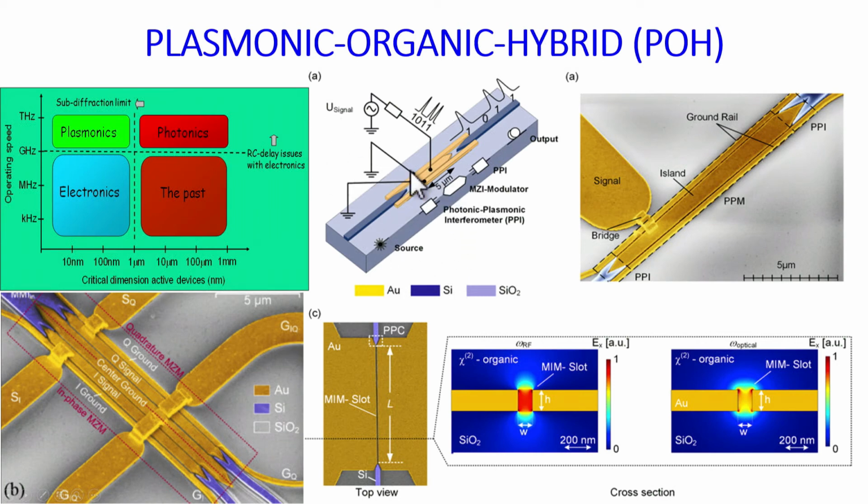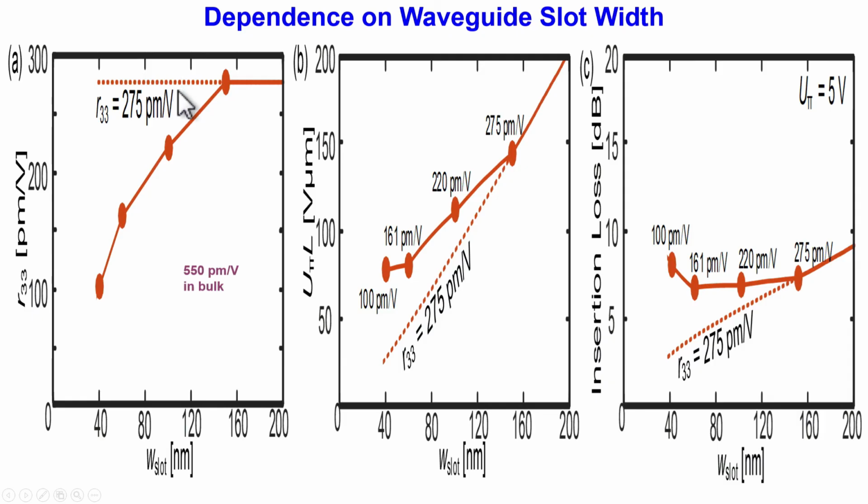I also show you a phase modulator, a Mach-Zehnder modulator, and an IQ modulator. And again, with plasmonics, you concentrate fields, both electrical and optical, in these nanoscopic dimensions. Of course, one of the advantages of plasmonics is that the very low RC time constants allow you to get very high bandwidth, and you can obtain very small sizes. The problem is optical loss, but there have been dramatic advances made in actually reducing loss.